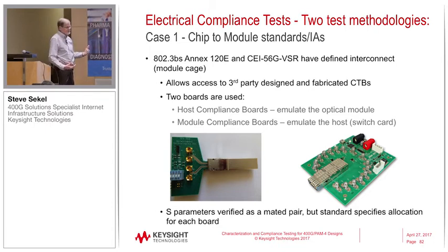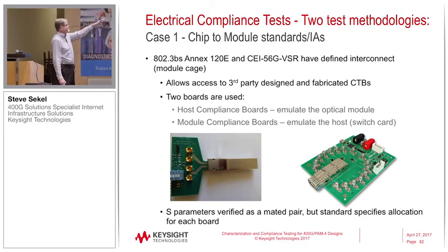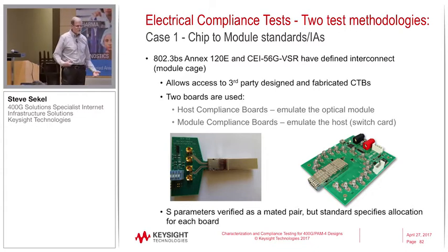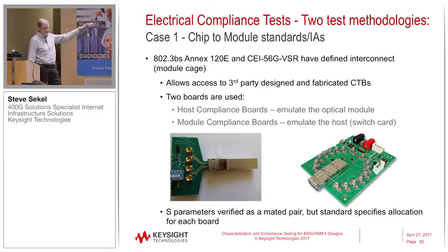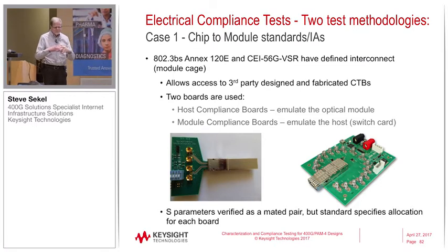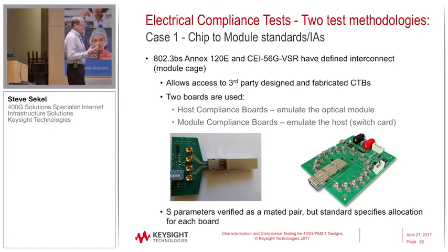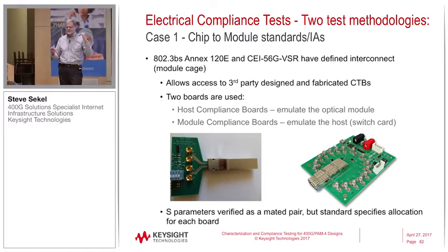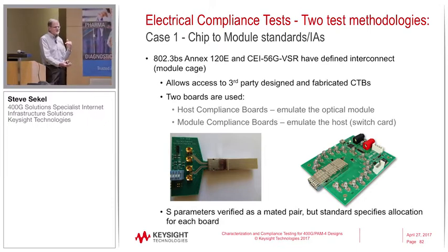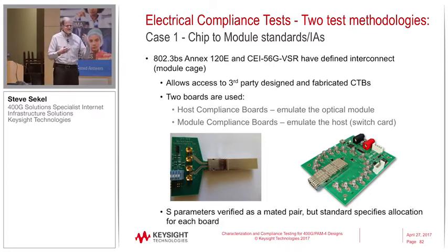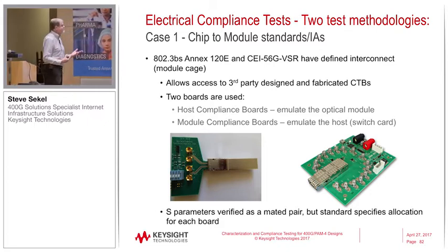with the standards around pluggable optics. So it's chip-to-module standards, and IA stands for Implementation Agreement. OIF documents are called implementation agreements as opposed to standards. And all of these have a very defined physical interface because the optics itself is set by an MSA, so not only is a mechanical package and connector specified, but the pinout is specified. So you might think the same holds for backplanes, but it doesn't, because that's a user-defined connector or an application-specific connector.